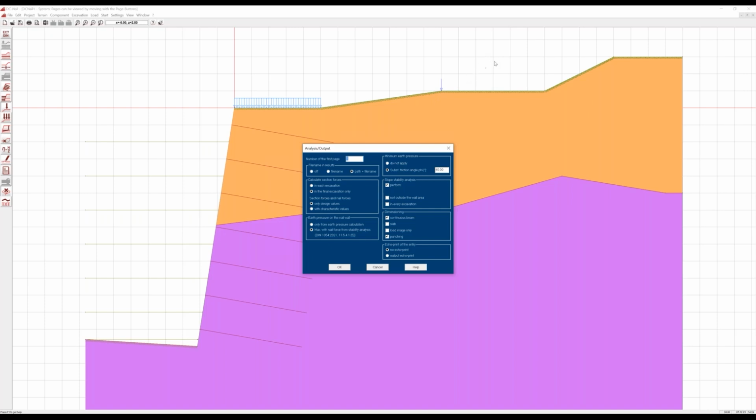The critical slip circle might be in this slope here, for example, but this is not what we want to calculate. We want to calculate the slope stability for the complete soil nail analysis, so we can check not outside the wall area. So no slip circle here in this slope, for example, is calculated, but only slip circles which cover the soil nailing construction here.